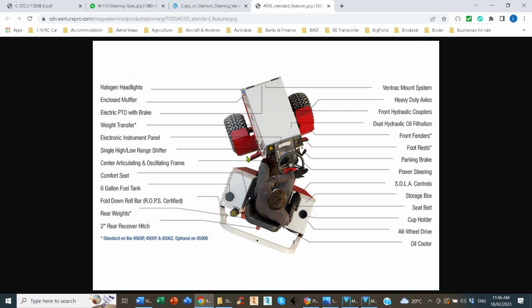Now, I chose not to winch it off, but at least 3 occasions I have got the chainsaw and cut off the sapling that was there and then driven out over the stump. It's a downside of articulated vehicles. If you park hard up against something, you can't get away from it. Because if you turn right with the front half of the vehicle, the back half is turning left and going into the obstacle. And obviously, with a single articulation, you can't do crab steer and drive off it.